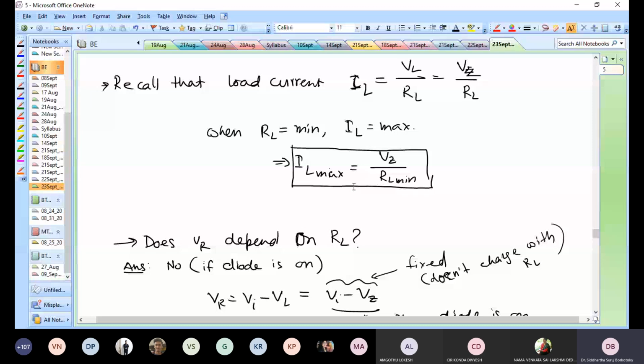But what happens when you exceed certain values? It depends. Many diodes will probably be able to withstand more current, since the power rating is sometimes much higher. So the diode might be able to handle a lot of power. If we exceed this Imax, it might still not get destroyed, though its intended operation might get a little shaky.